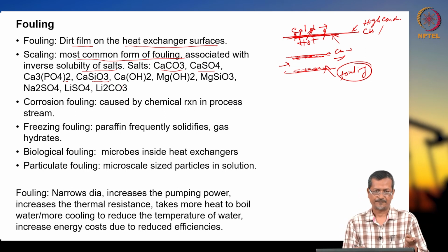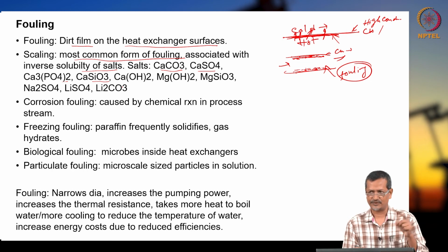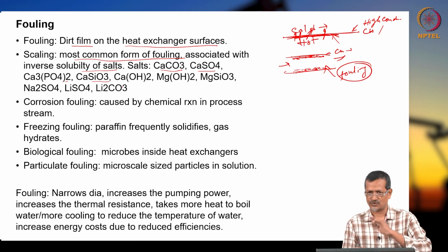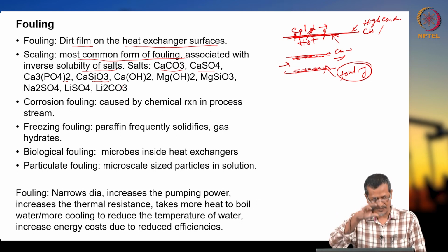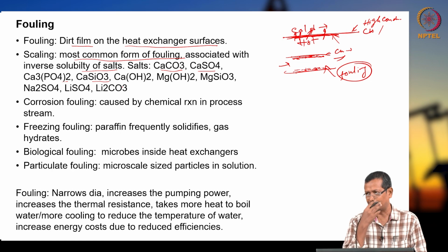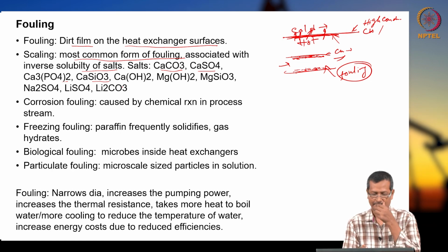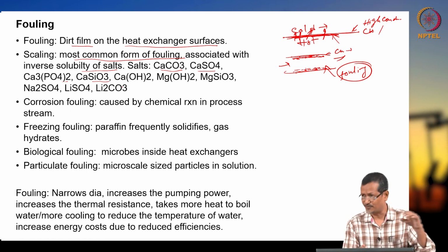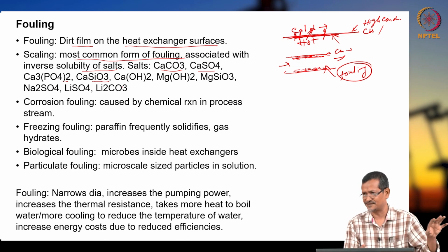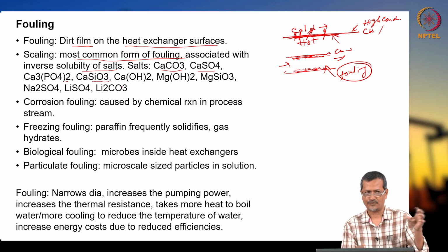Okay. So normally in boiler and thermal power plant applications, what they will do is remove all the debris, salts, everything from the water, then they will use it. First they will be removing all the salts, then they will be using it for heating purposes. Okay. Then if you do not have any extra salt or dirt, there will be no deposition. But in many cases it may not be possible. So in that case you have to do a cleaning operation, or you have to replace the whole system.